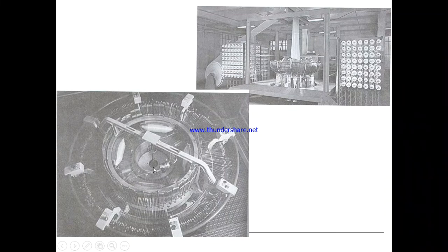More than two shuttles can be used depending upon the circumference or the diameter of the fabric, and all those shuttles will rotate and continuously insert the weft yarn. As soon as the weft is inserted inside the shed, it will be beaten up by the antenna.